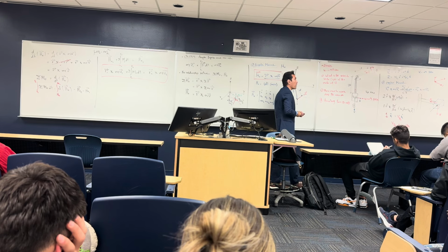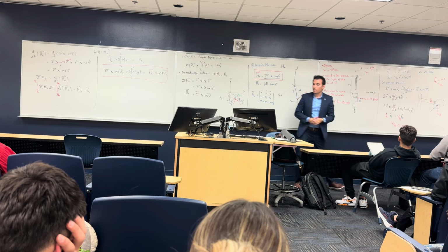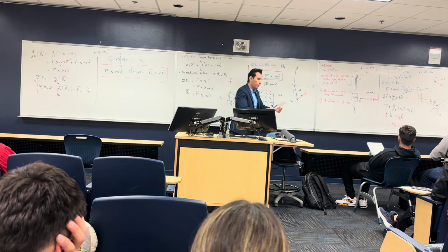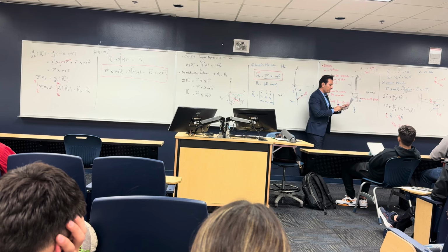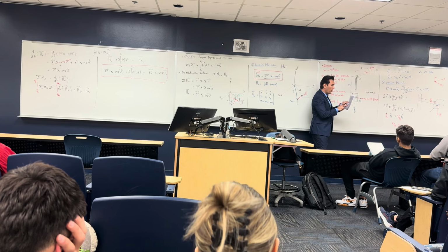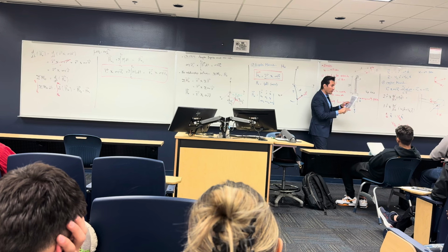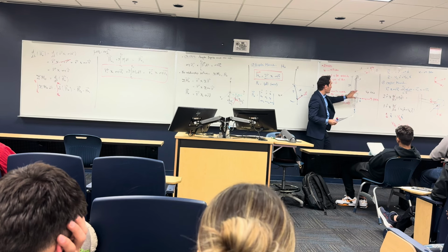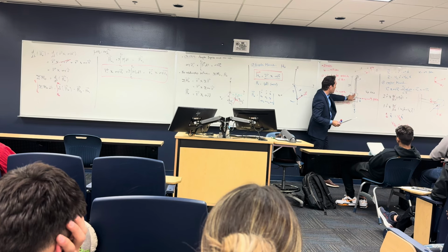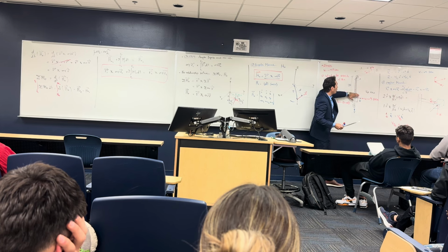How about VR? We've got the component v theta. Actually, that's why we need to read the problem carefully. It says that just after an arm begins pulling the crate from R1, 2 feet, to R2, 1 feet, with a constant radial velocity, VR equal 0.4. So this arm is moving toward this direction with 0.4 all the way constantly.